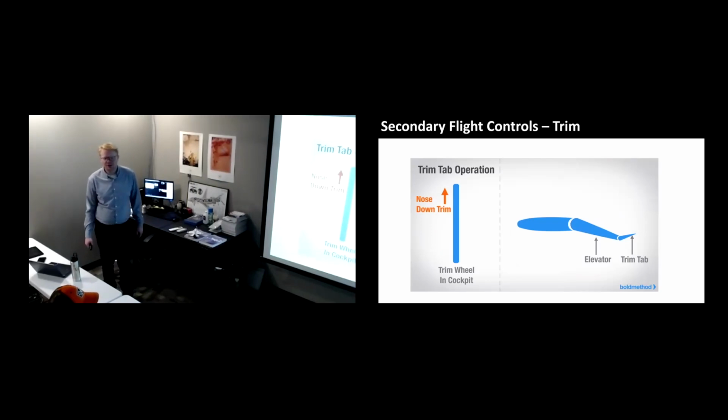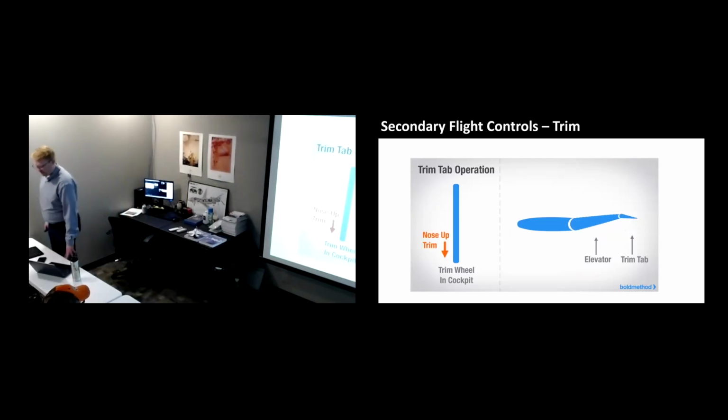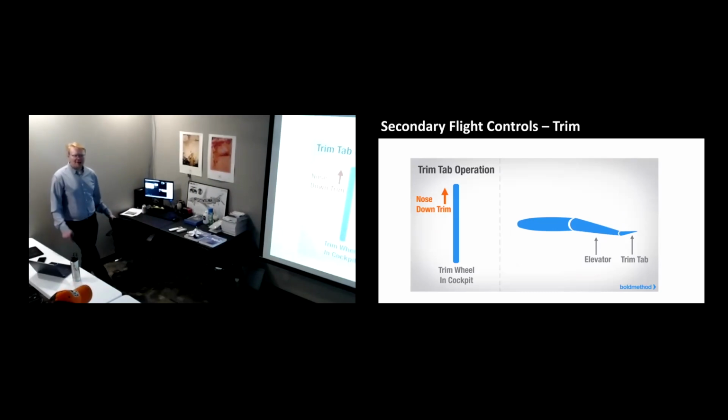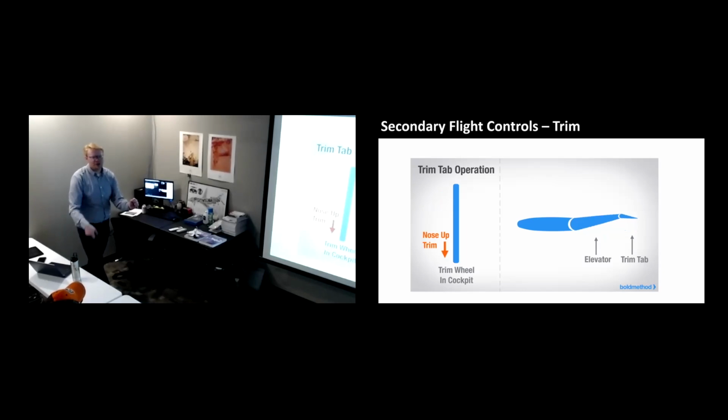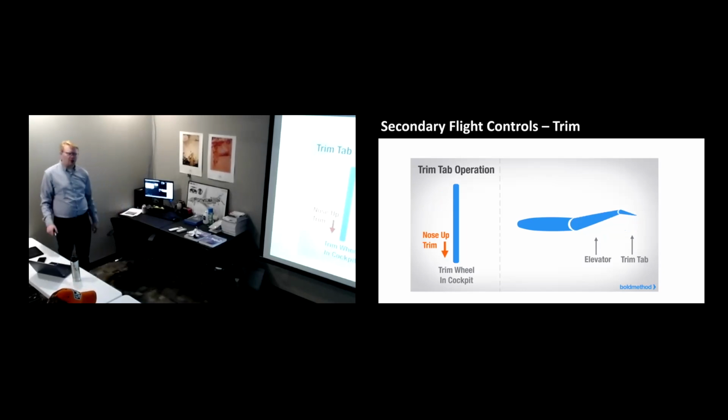This is a good video, all things considered. So you'd see the action on the control stick. You could feel the change in the force of the input as you move the trim wheel. We'll say in flight training like 1,000 times, but you really never want to be flying the airplane out of trim. Meaning if you're pushing the airplane down and you're having a lot of force, you should probably give it a little nose down trim. It reduces your input and keeps your workload down.